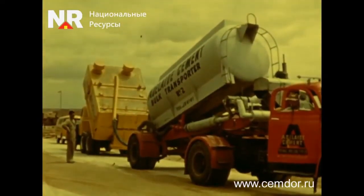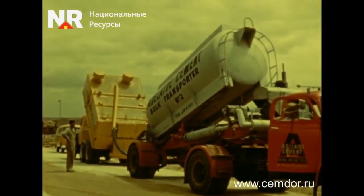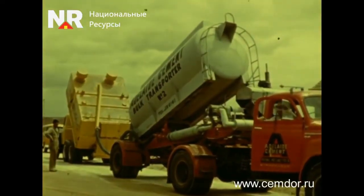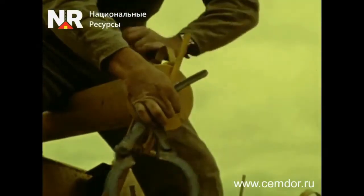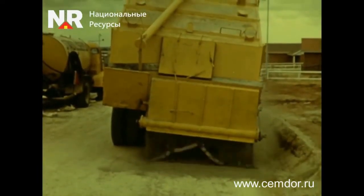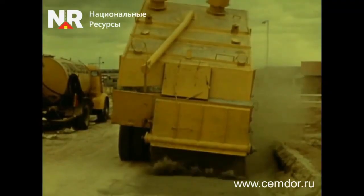Cement distribution can be carried out using a cement truck in combination with a mechanical spreader. The cement is fed from the cement truck into the spreading machine. As it moves along the roadbed, the cement spreader applies the cement in an even layer.